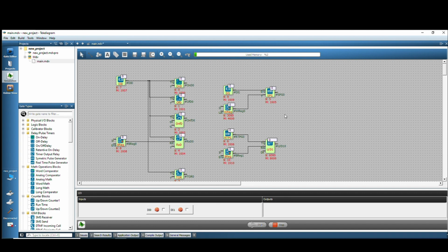In the symmetric pulse generator, it toggles low and high at half the period duration. Therefore, if you want to generate a pulse per second, you need to enter 500 milliseconds. Let's start with this example. When I activate digital input 1, it will start at position 0 for 500 milliseconds, then switch to 1, 0, 1, and continue generating pulses until a signal is received at the active input.